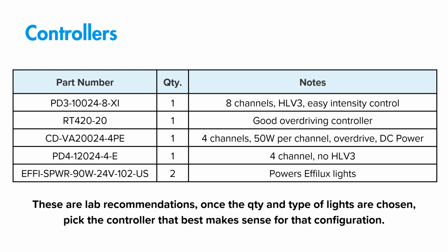It just plugs into a wall and gives you one M12 connection that you can plug your light into, and your light will be on. Otherwise, Effilux lights do work by plugging them directly into a power supply, and then you have a little bit more control with the pinout as well. So if you don't want to get a dedicated Effilux controller, you can just get a power supply for the lights instead.